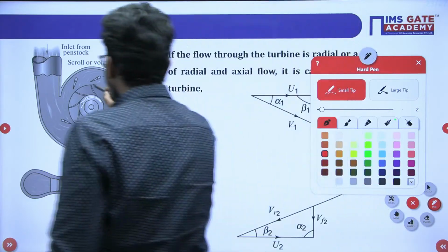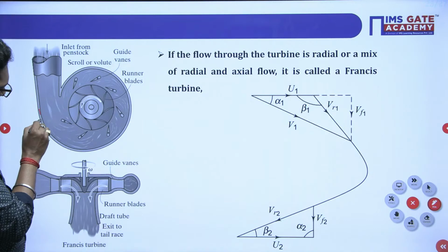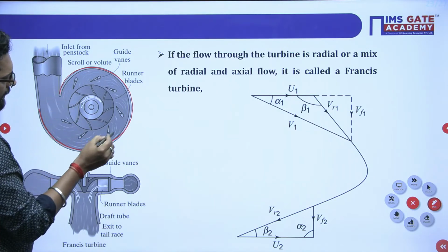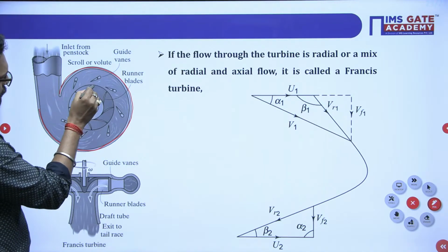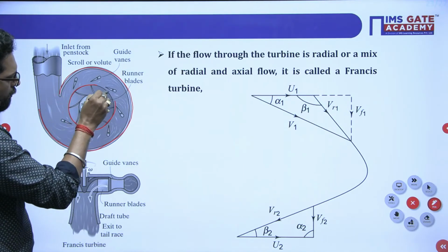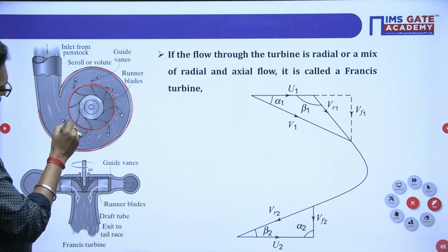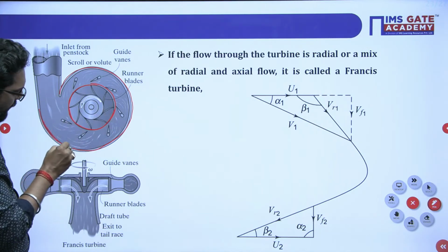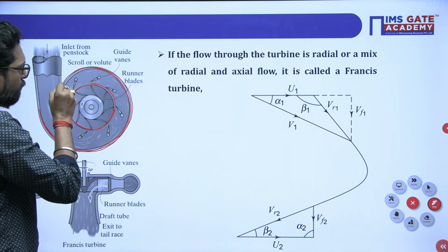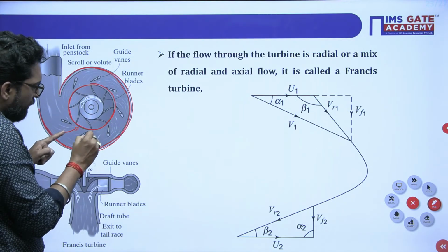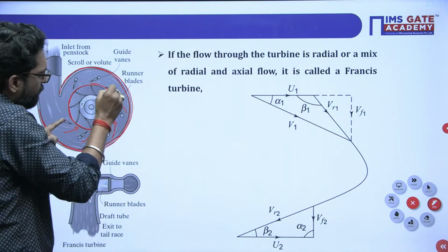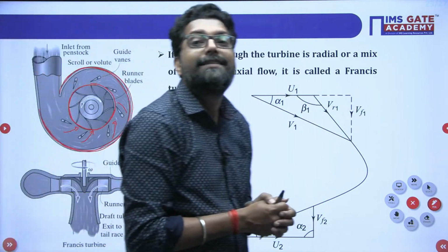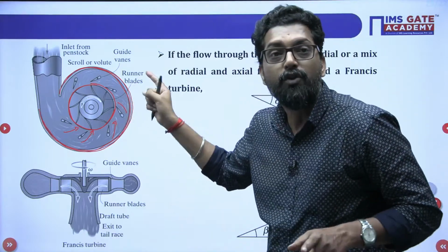So see this one. This casing, the area. This is your outer casing, the outer volute part, and this is your rotor. So see this area, beta. The wedge shape is there. See, the area of the passage will continuously reduce so that the velocity is uniform throughout. Why? Because there is frictional loss. If the fluid is moving, energy will be lost. So who maintains the energy? The shape of the spiral case maintains the energy. So in this case, we have to use the volute casing.